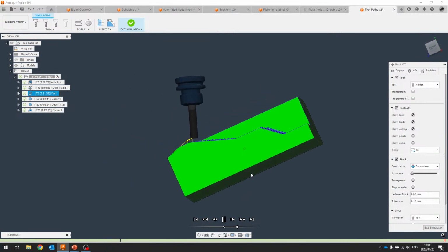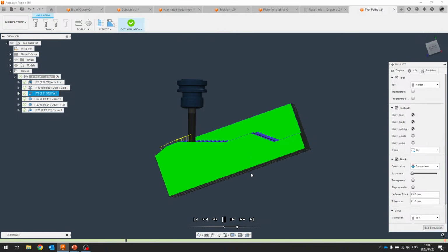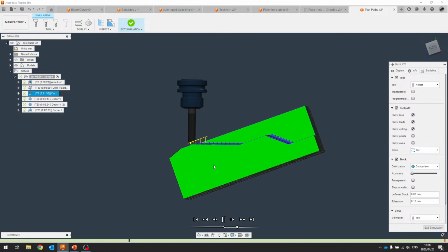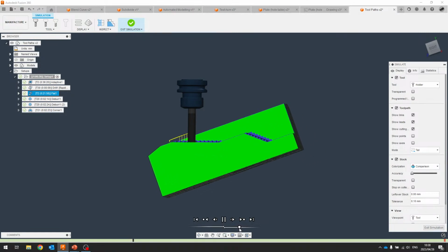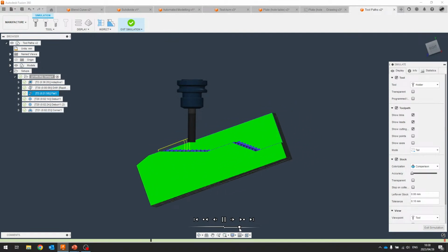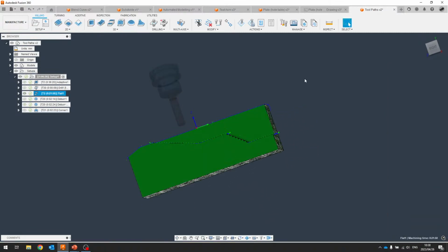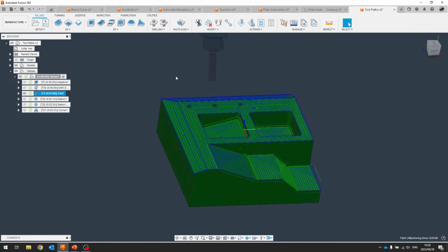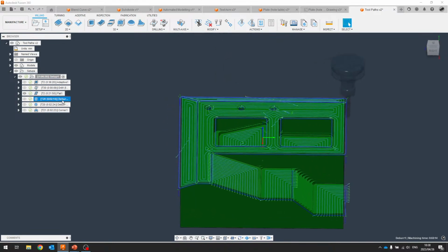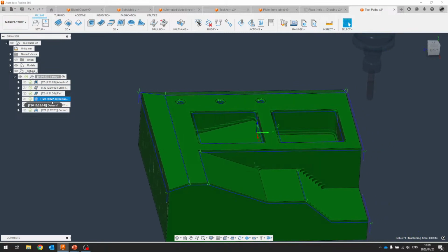Let's try and get that tool vertical. So if I have the tool vertical as if it was staying stationary and you had a bed machine with 5 axes, we can see how the part tilts to then machine those various faces. Okay, so that's your inclined flats option. We'll move on to the deburr and switch the inclined flat surface toolpath off there.